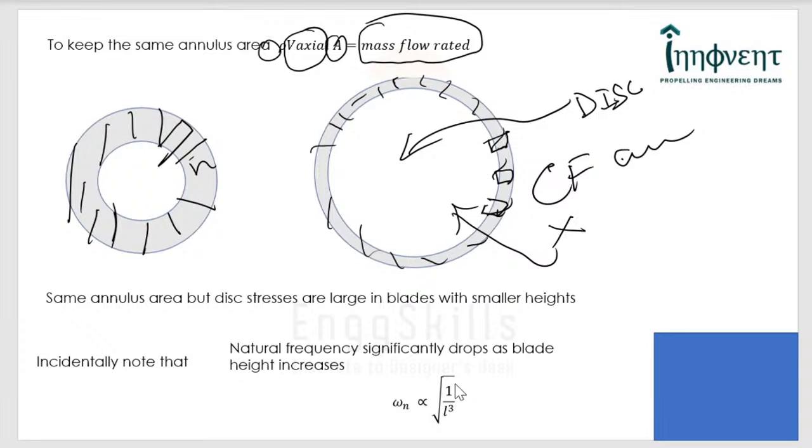And incidentally, note that the natural frequency of blades is proportional to 1 by L cube. So that criterion also influences the choice of blade height.